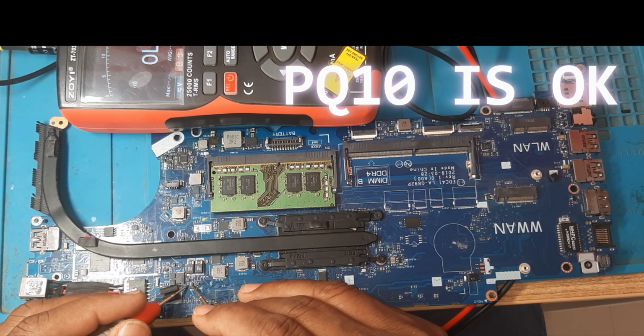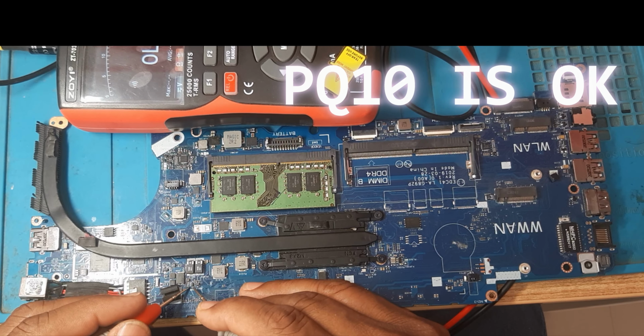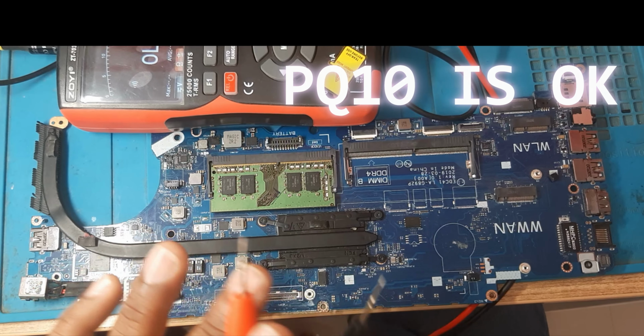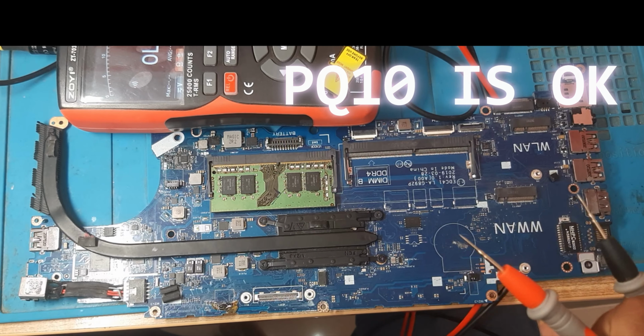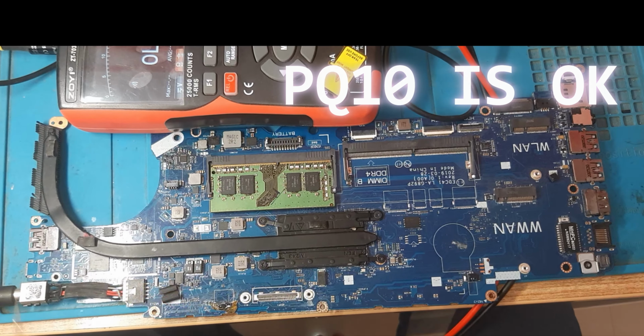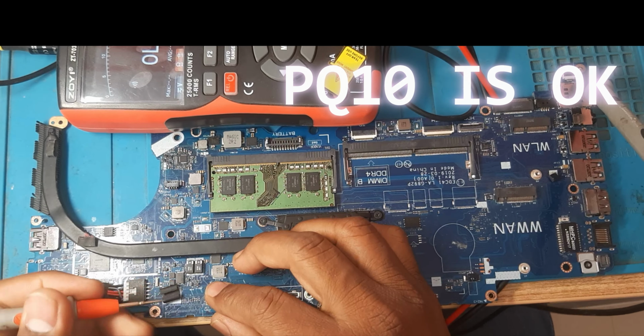What I am saying is, if pin number 2 has voltage, then all the rest will be ground, and pin number 3 should also have voltage. Whether that's happening or not, I will give the supply and we will check. Giving the supply. See here, one by one I am checking. Pin number 1 is anyway ground.